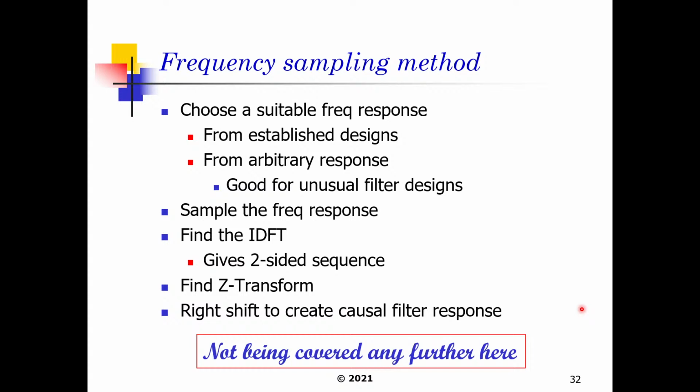Whereas for the magnitude, it was just a constant multiplication factor, a constant division factor, or constant attenuation factor for all frequency components. When we moved on into the FIR filter design, we saw that if we started with an ideal low-pass filter response, this is actually for infinite impulse response filter design in particular. So to move from that being an infinite impulse response to a finite impulse response, when we use the time sampling method, we basically impose a window of n samples here to enforce that instead of going towards t equals infinity, it now goes up to t equals n, where n is the number of samples. And applying this windowing technique here, we impose a period of n samples upon the signal for our low-pass filter design here, and in creation of the FIR filter, we see here that in doing this, we get the spectral leakage or the aliasing effect as a result.